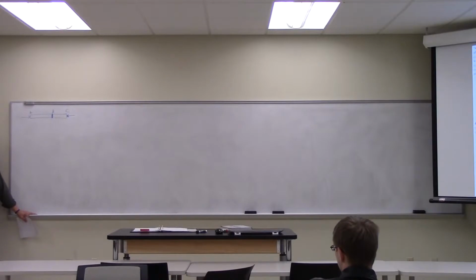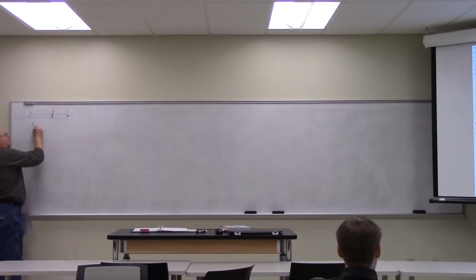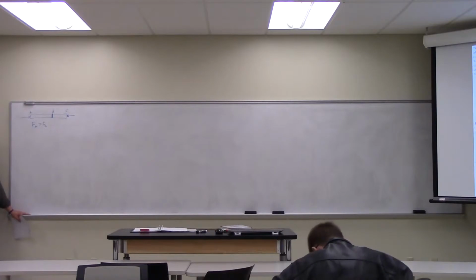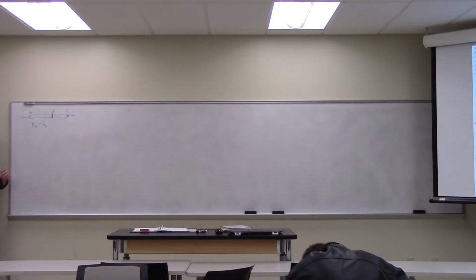It is indeterminate. But what do we know? The sum of forces in x equals 0, right, so we know that FA is equal to FC, because I've drawn the vectors and their orientation, so I don't have to worry about the sign of the forces. The magnitude of the forces is equal, and the direction is captured in my free body diagram. So we know FA equals FC.